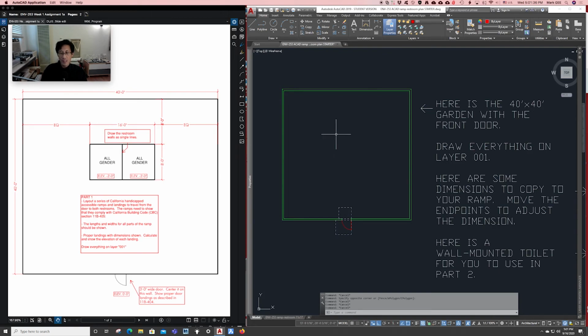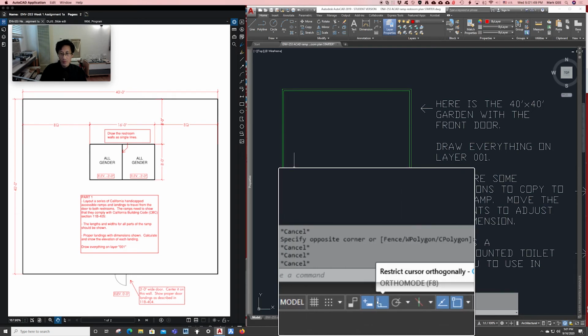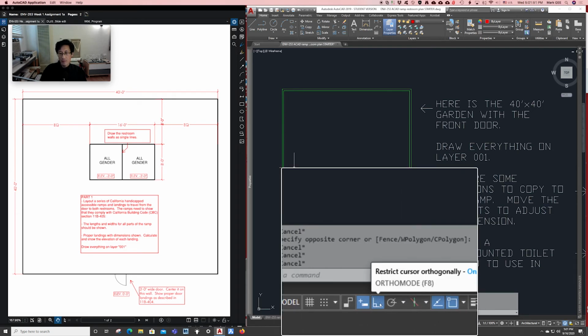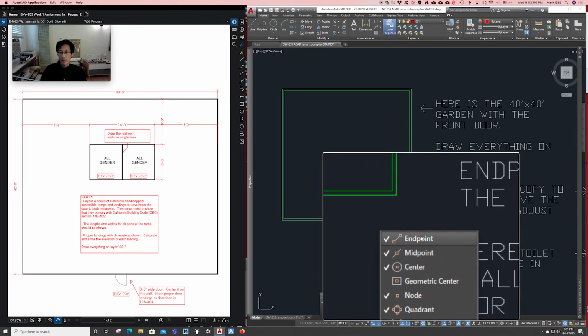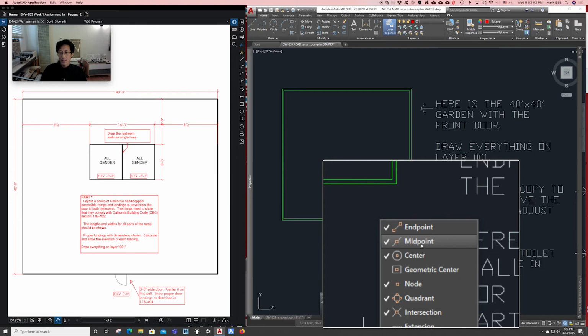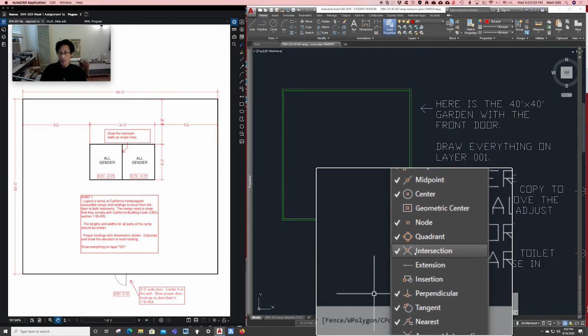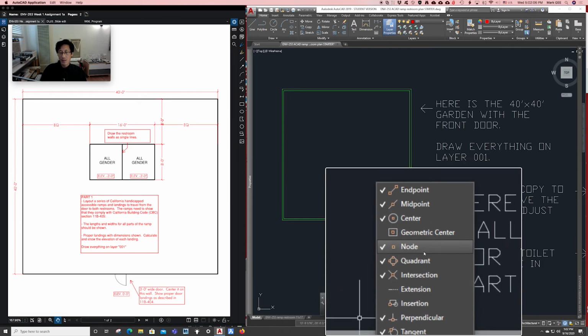Okay, so we're going to use the line command to do that. Just do it a couple times. We'll do the line command, and then we use the Polyline to do the same thing. Again, make sure that right now that your ortho snap is on, because we're drawing in all right angles, okay, and that the object snaps that I recommend having on would be endpoint, midpoint, and intersection, which are the ones that I recommend for this exercise right now.